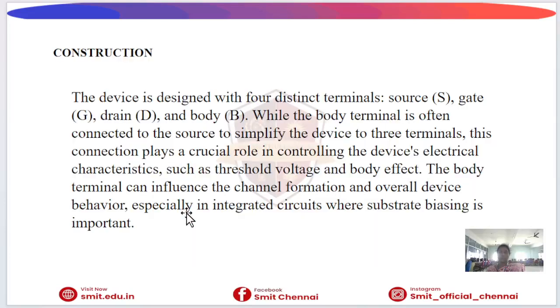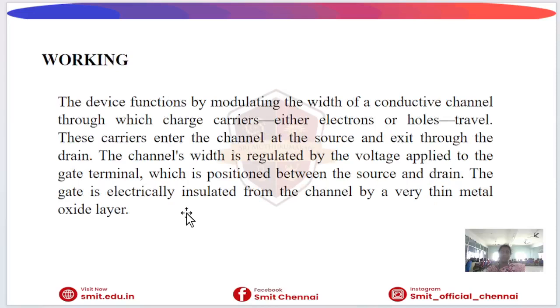So this is the construction, and the working is: the MOSFET works by controlling the conductivity of a channel between the source and drain. So the gate voltage determines whether the channel exists or not. The gate voltage only decides whether the channel is carrying a current or not.